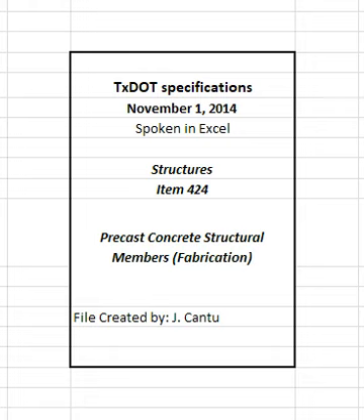When field conditions are such that evaporation of water from the concrete makes the surface finishing operation difficult, a fog spray, fine mist, of water may be applied above the concrete surface. Do not fog directly toward the concrete or in any manner that will wash cement paste from the fresh concrete surface or cause water to puddle. Do not fog as a means to add finishing water and do not work moisture from the fog spray into the fresh concrete. An approved evaporation retardant conforming to DMS